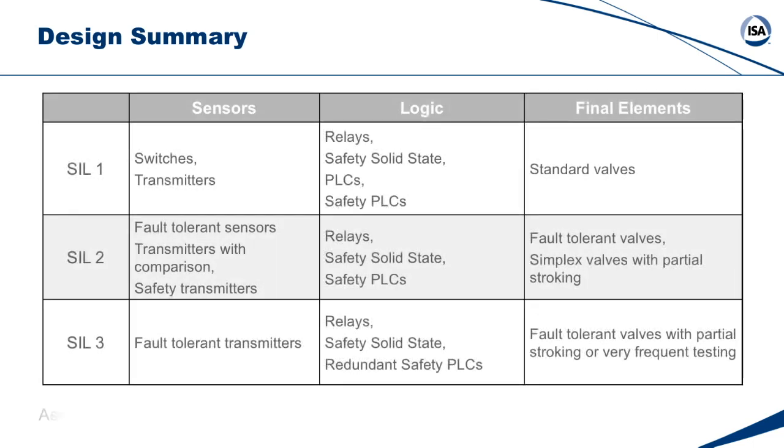And then when it comes to designing systems, what will you actually do to meet SIL 1 through SIL 3? SIL 4 I basically don't even show because no one would recommend having SIL 4, and it's just incredibly difficult to design. And in reality, it's not even possible if you want to include human error rates and maintenance issues and people leaving things in bypass and not following procedures. Most people just simply do not design for SIL 4 and would redesign the process to be inherently safer, add other safety layers, so you don't even have a SIL 3 requirement, let alone SIL 4, because you'll see here how expensive and difficult SIL 3 is.